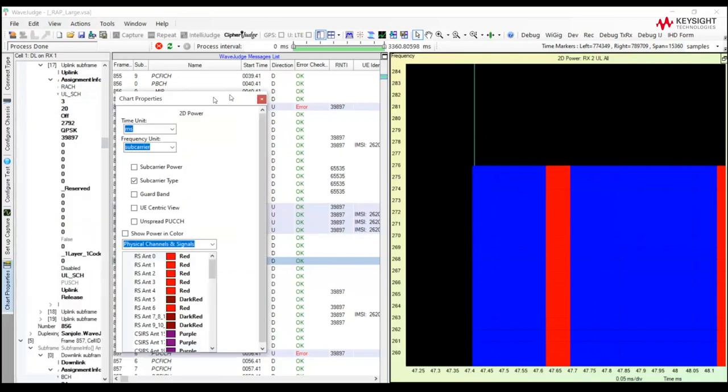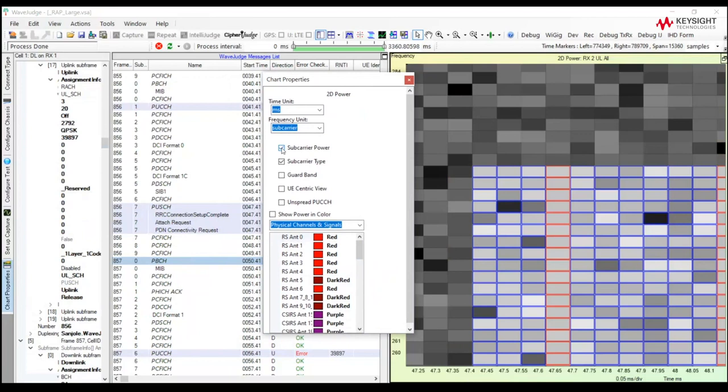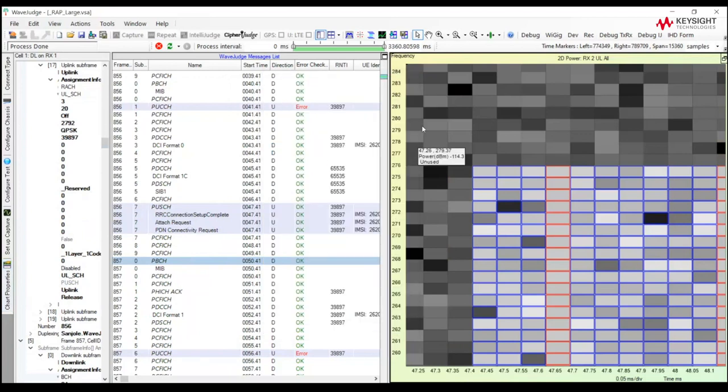And remember what we did before. We also can overlay on top of that the actual RF transmission of the UE. Does it overlay perfectly with the resource elements of where it should be? And we can see here that it does not. The first thing we see is that for all of the uplink transmission, all the blue blocks, some of those resource elements aren't even being used.